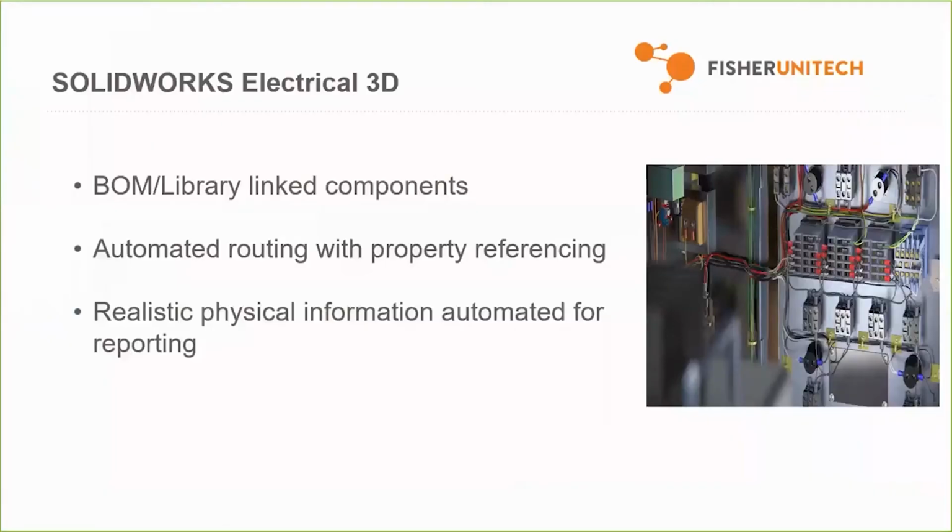So with that, let's go ahead and address SOLIDWORKS Electrical 3D. SOLIDWORKS Electrical 3D sits on top of an existing mechanical seat, and what that means is you are now able to connect all that schematic parametric information to your mechanical environment. So no more do you have to complete your schematics, give a schematic or a bill of material to your mechanical individual. He has to go through all of his folder structures to find all the parts and place them. That's all going to be handled for you. It's going to hand the proper parts to the mechanical side, so now he can route that information.